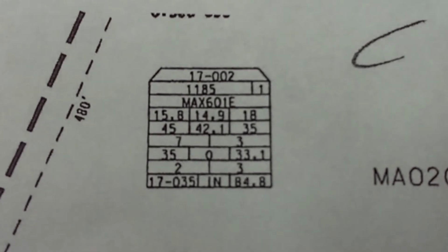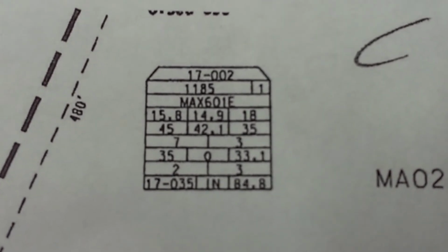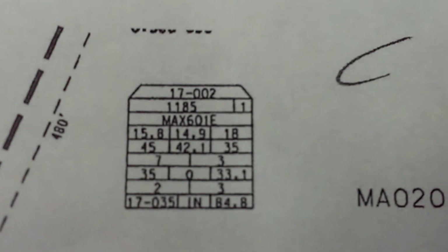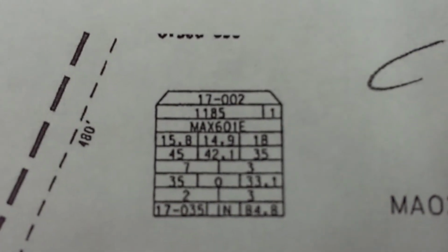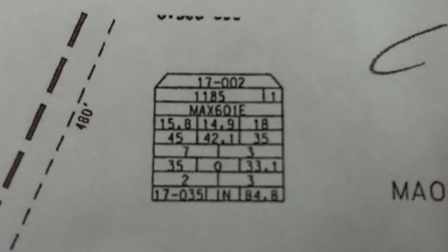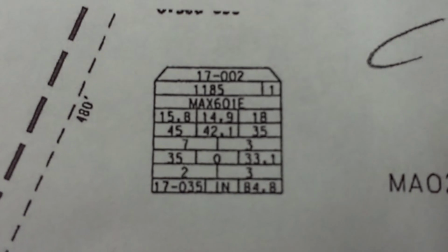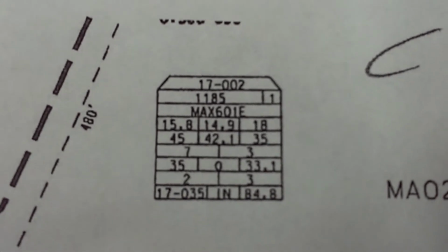What's good about that is if I see a 0 and a 1 in there, that tells me that I can't cut anything into that plant from the node to that amp. I've got no wiggle room. I'm screwed. If I have to cut a tap in because somebody built a new house, I'm building cable. That's the concept. That's where I look at it, all right?